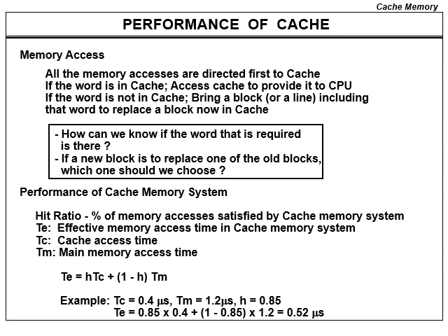Now what happens is, whenever there is a cache miss, that means the data that is required by the CPU is not available in the cache memory, at that time the CPU goes to the main memory and reads not just the piece of information which was required, but the entire block.